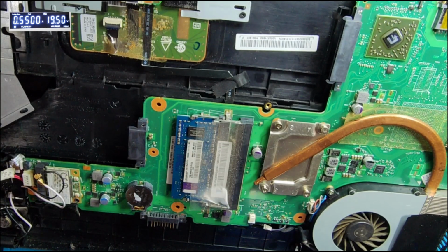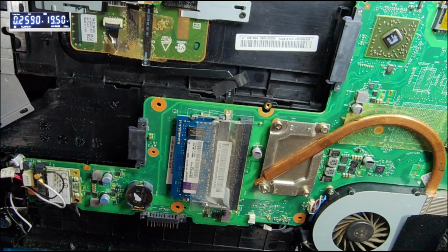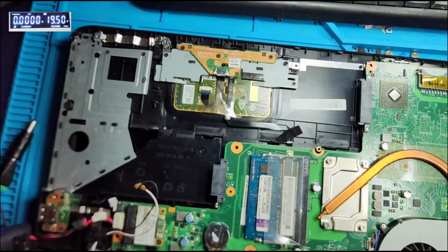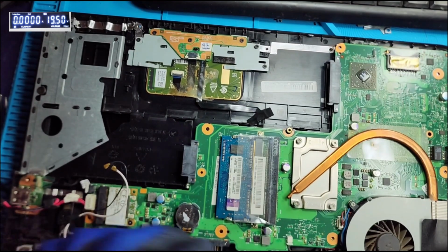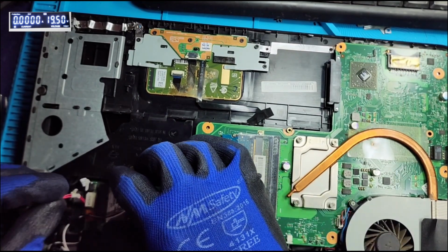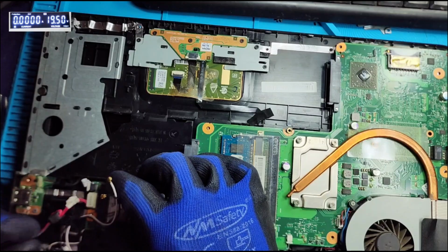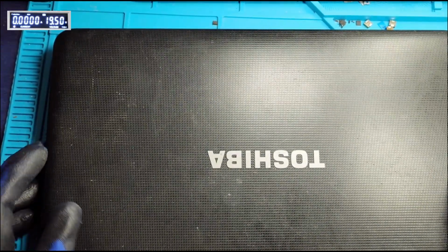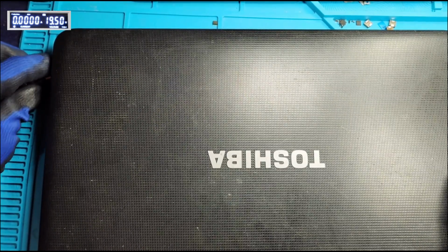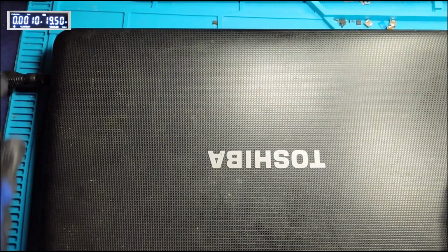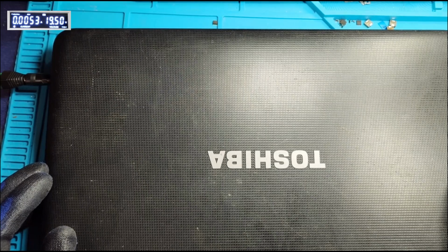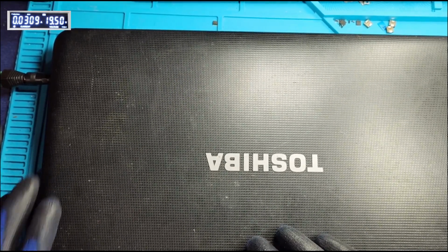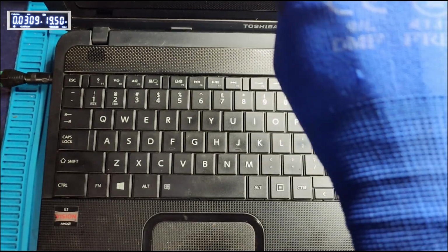Okay, I'm happy with that. So I'll just try to assemble everything inside the laptop and go for a last check. I hope everything should be working fine. Alright. Okay guys, everything is assembled inside the laptop. So now look at the display of the power supply. Now I am going to connect the adapter. Okay. Right, the adapter is connected and you can see the amperes drawing around 30 milliamps. Okay. So now let me open the laptop and press the power button.